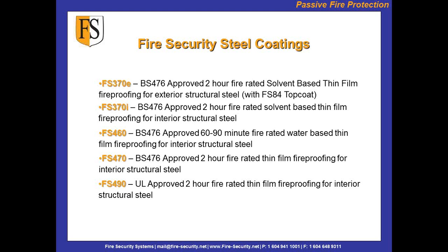Question, do all those intumescent coatings start reaction at the same type of temperatures? Yes, they do. They all run the 80 to 90 degree mark, Celsius. That's when they actually start to activate and start to protect. So our 370I is our indoor solvent-based thin film coating.